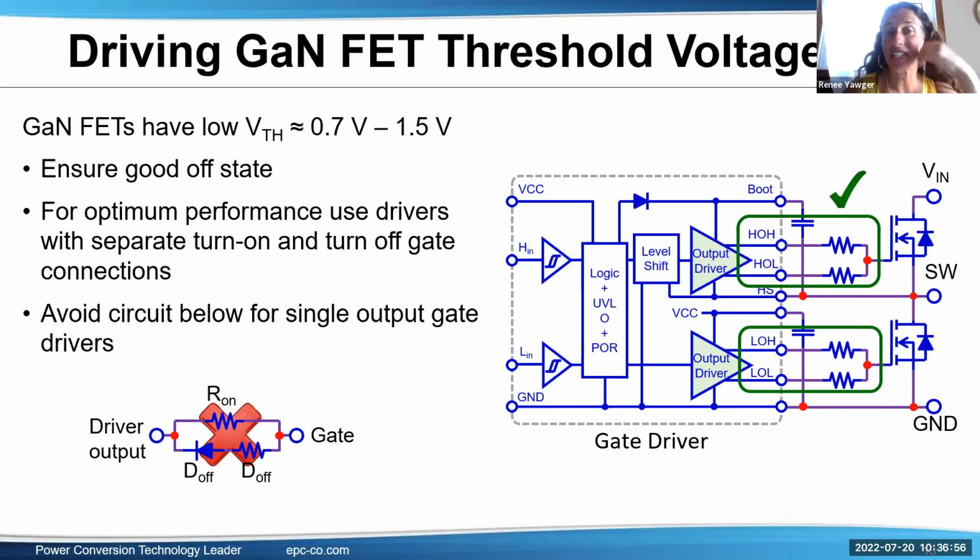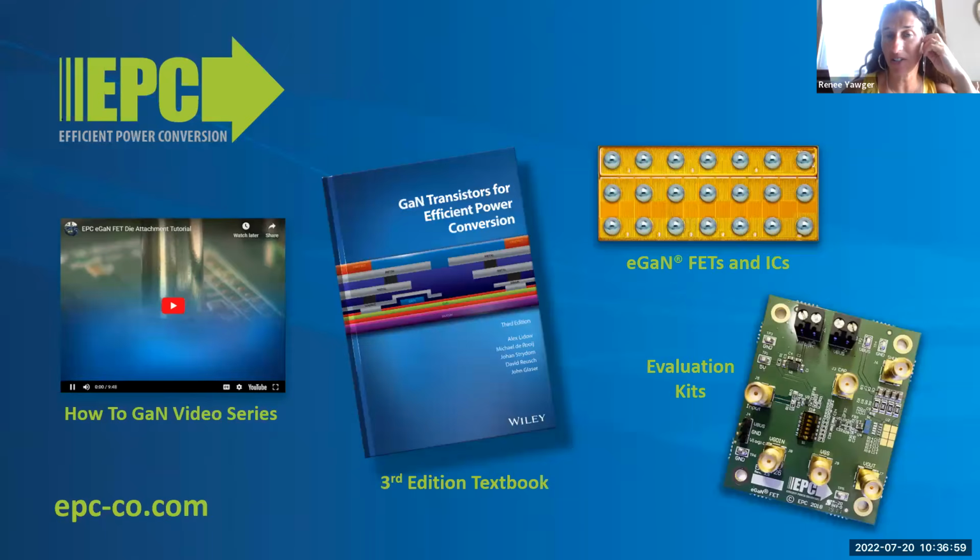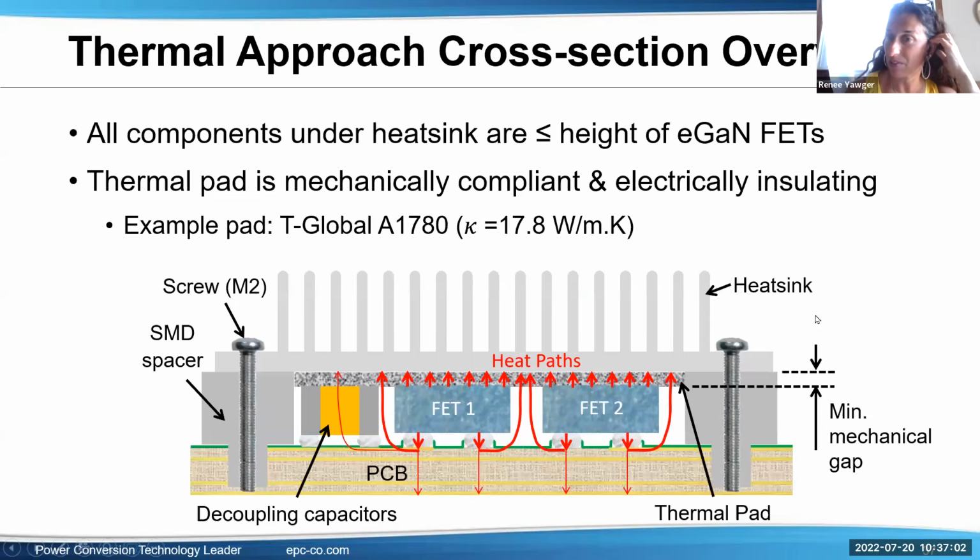On slide 37, you're showing capacitors, and the statement is that the area will get very hot. Capacitors are usually rated from 85 to 125 degrees, so is that an issue? It's something good to check into. In a lot of cases, even though EPC FETs are rated higher, a lot of designers choose to do 125 degrees C max on the junction and keep the heat sink noticeably cooler. That is a good point, to keep the capacitors in an acceptable heat range.